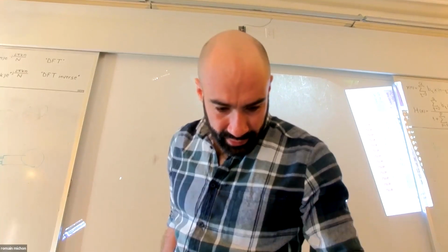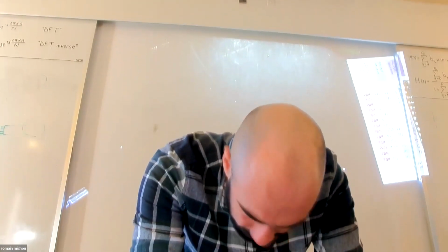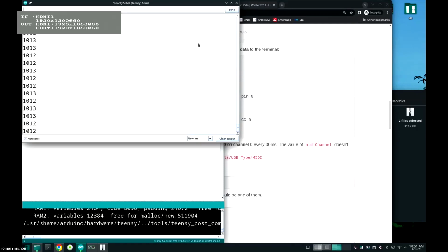well, it's not really doing what I want, right? Okay. Oh, sorry. So, see, it's kind of giving me something. It looks like when I'm pressing, something kind of happens, but it's not very usable, okay? So the reason for this is because I'm missing a ground, okay? And how am I going to add the ground to this?